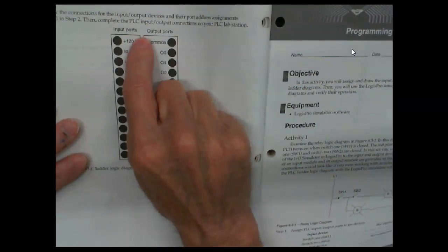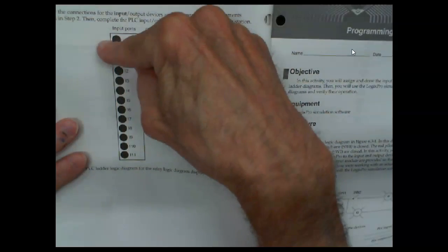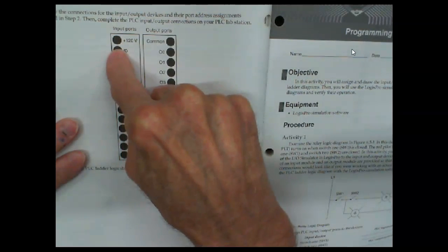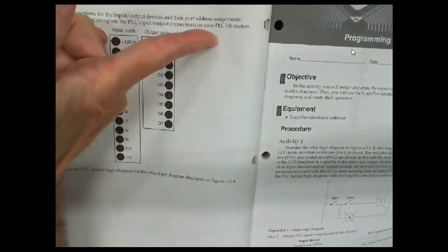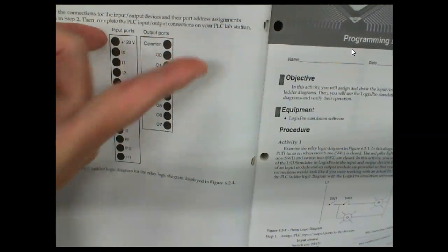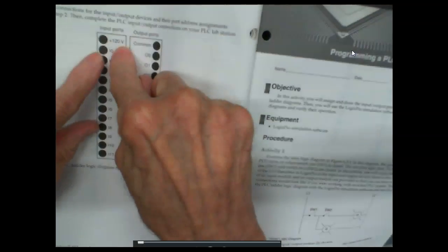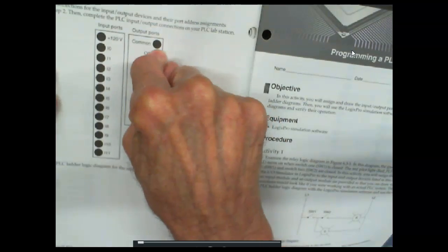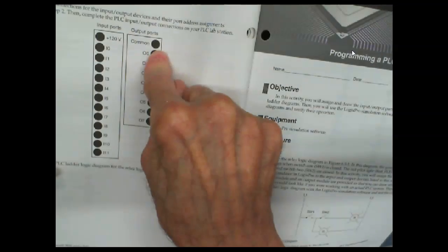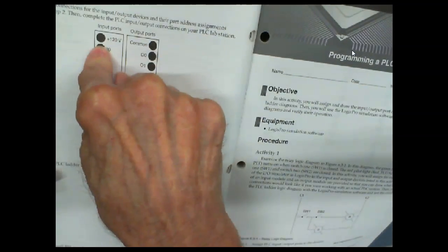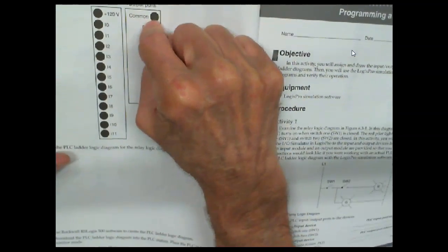So that means you're going to mark this common out. You're going to draw a wire out here. You might have to bring it up because this guy right here gets pretty close sometimes. And then you're going to draw the negative toward this. And over here, the negative is going to point out, because we're running sinking inputs and sourcing outputs on our PLC. Sourcing outputs, sinking inputs.